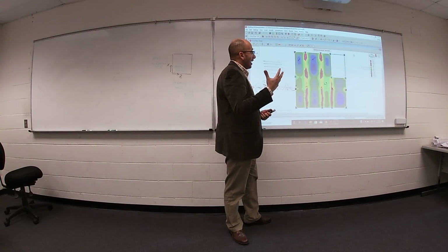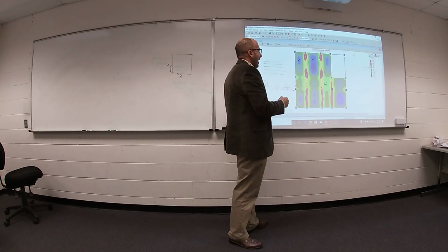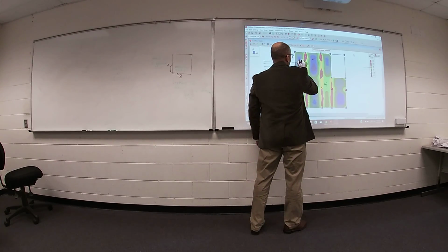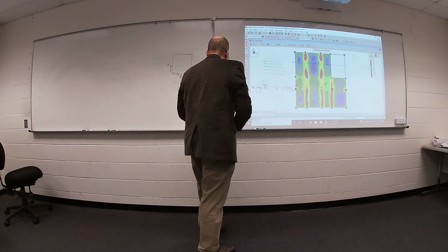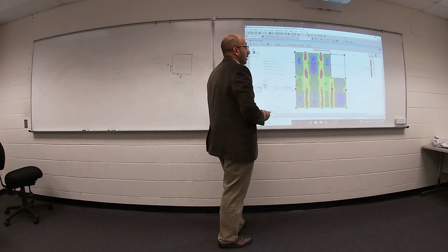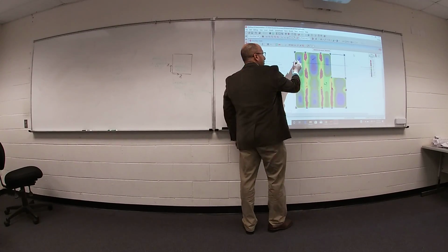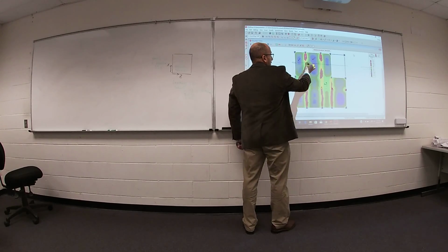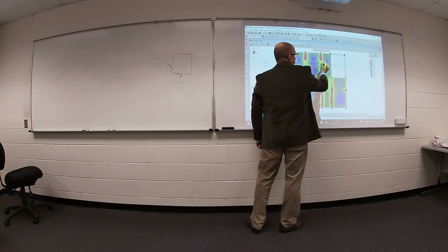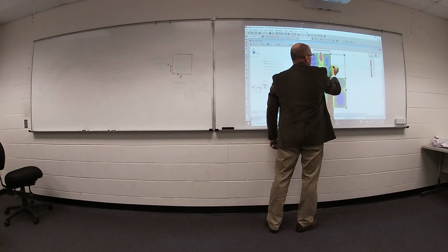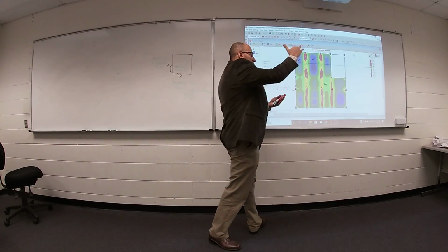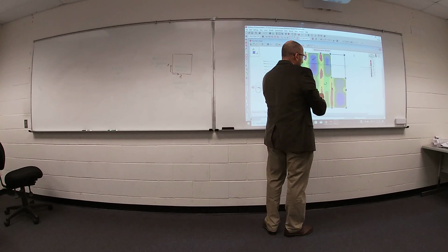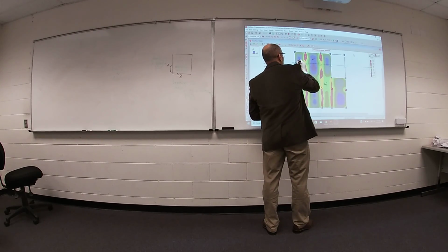So we learned it in structural analysis. If you take a strip like this, your slab is supported on the beam, supported on the beam, supported on the beam. We learned that if you have a distributed load on your beam, your bending moment diagram looks something like this.